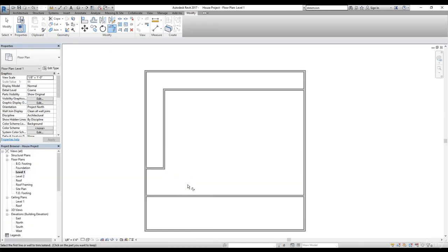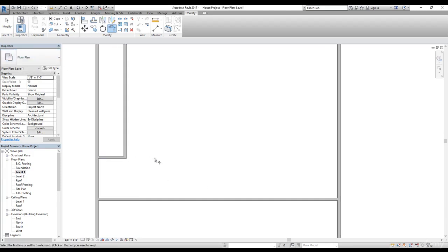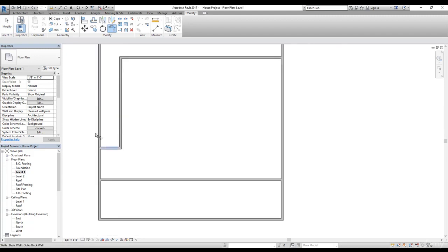Now we have set up this garage area, and we can use the offset for our other walls which are going to be inside the house. There's one more thing I want to do here: because this is going to be the outer wall, it has the same wall material. So let's make the garage first, and then we will use the different wall. The garage width is going to be about 18 feet. So I'm going to create another offset. Let's select Offset, type 18, press enter, select this wall, click here. That's going to be our garage area.